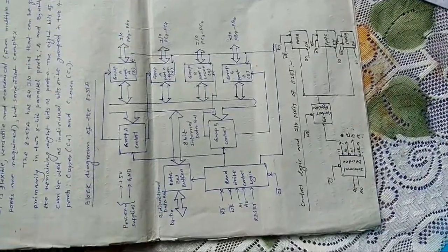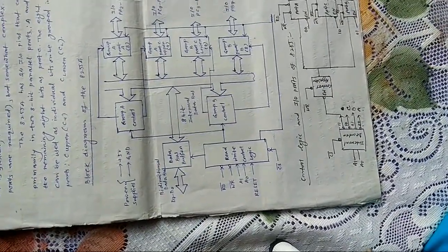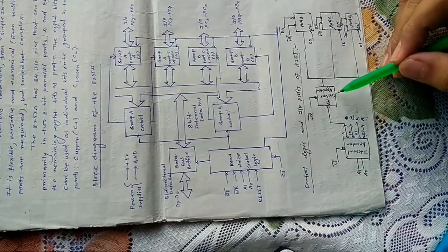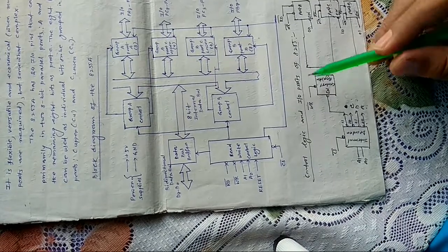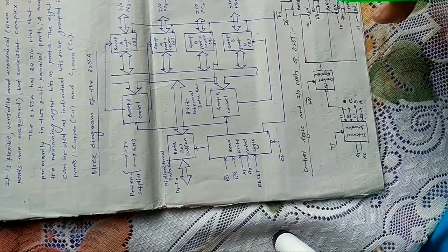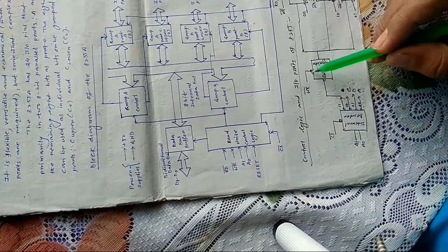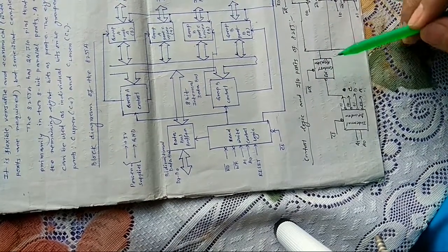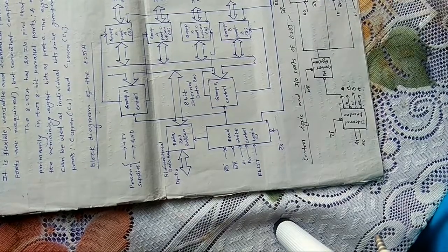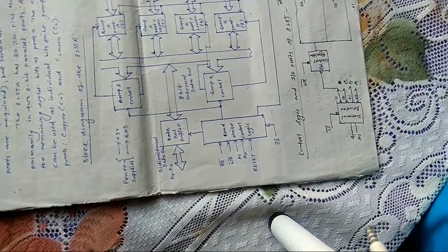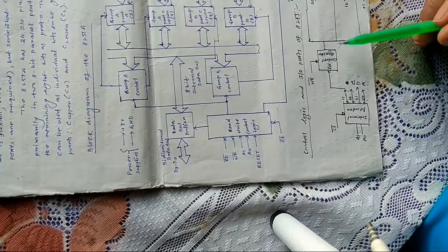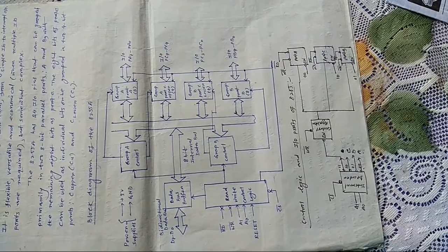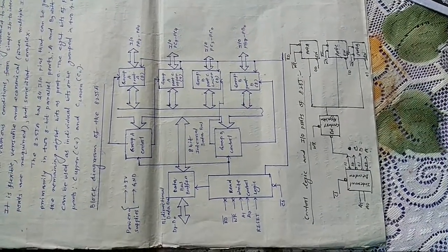So that means this time the control word will be stored into the control register. So actually the control register is an 8-bit register where the control word is written by the programmer, and that will decide which port is used for which purpose. Okay, so you will understand this properly if you know the format of the control word. So that I will discuss now.